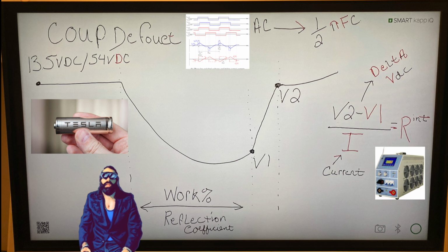And I'll give you an example. Let's say a conductance-based meter or impedance meter is injecting a 1 amp AC sine wave across the battery terminals. Well, if you have 5 or 6 amps of harmonics, AC harmonics riding in the DC bus, either feeding back through the switchboard power supply through the inverter, sinking back into the battery system.